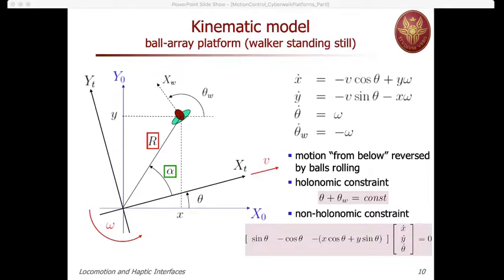So if you are able to impose some x dot, y dot, automatically theta dot will follow, and this in an instantaneous way. Of course, by doing maneuvers, as we know, in the presence of a non-holonomic constraint, we still can reach any final configuration x, y, theta.